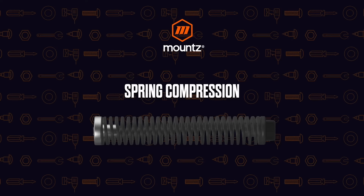Most, though not all, screwdrivers and torque wrenches for torquing processes use a spring, and the spring's constant rate of compression gives the ability to generate a specific torque value. As we compress the spring with our turning or twisting force, this allows us to accurately deliver a specific torque.